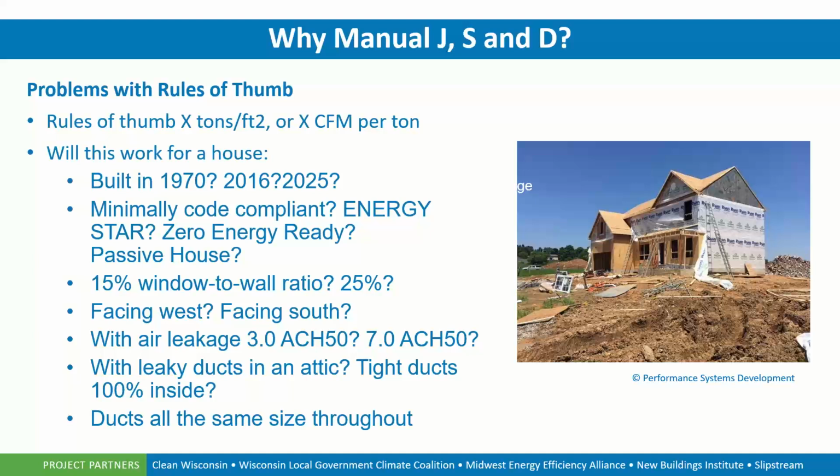Is there a difference between the house facing north or east or west or south? Based on the glazing, if the back of the house is a full glazed wall and it faces south, it's going to have significant heat gains from the sun, from solar activity. If the back of that house faces north, we may not have as much in that solar gain calculation. And that's what the Manual J takes into account.